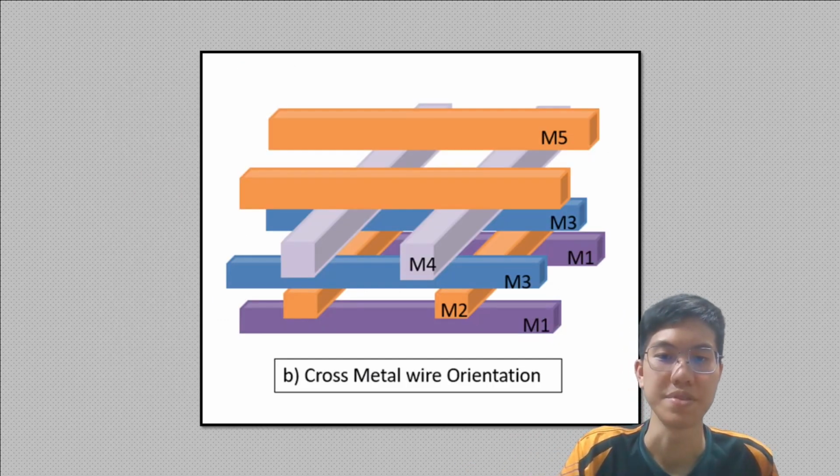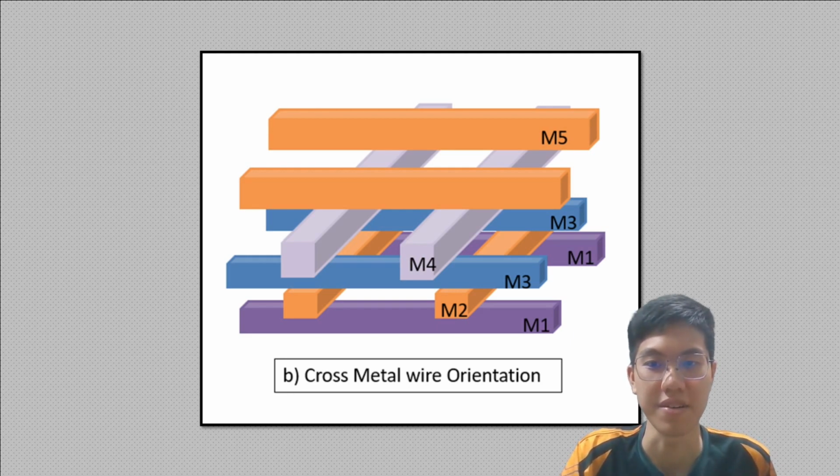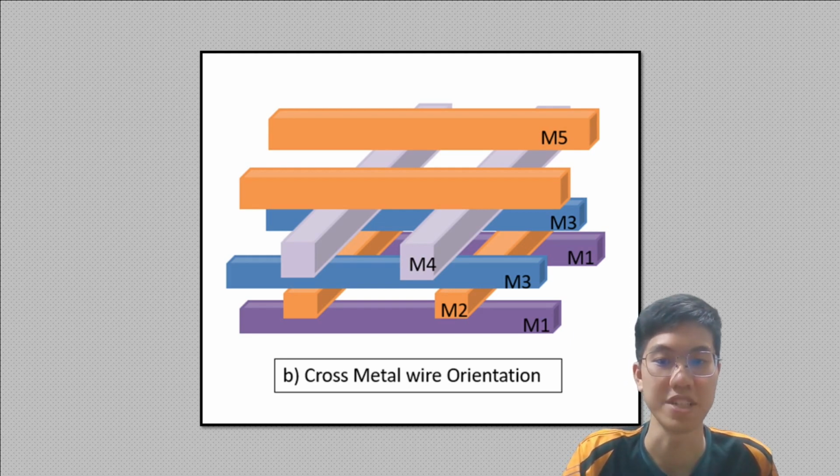Another important point to note is the metal layers are drawn such that they alternate in direction. For example, the lines on M0 are drawn horizontal, M1 lines are drawn vertical, and so on. This is to make sure metal layer routes are kept away from each other to avoid congestion and to reduce crosstalk.